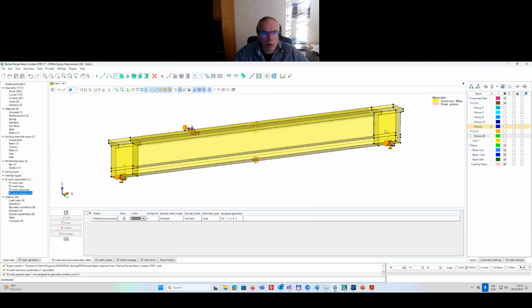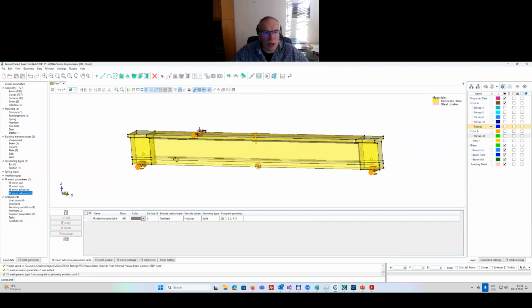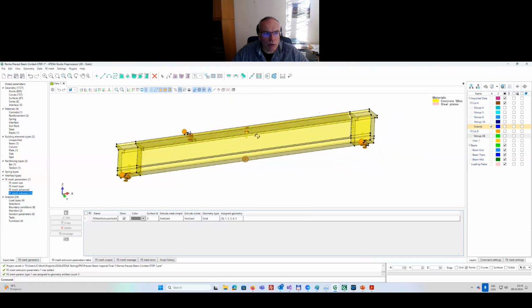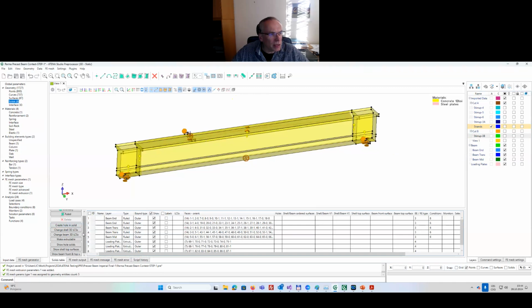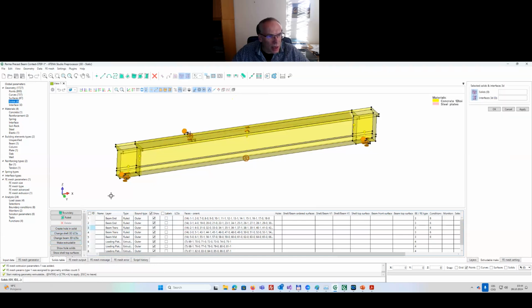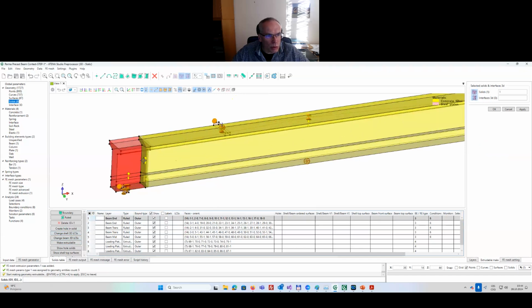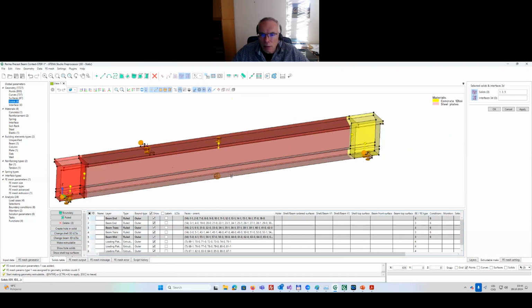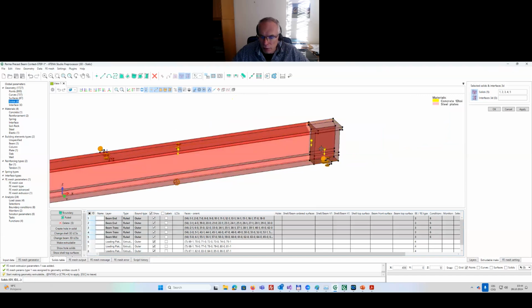We want them to be extrude, but to be able to use extrude, we need to make sure that all these regions are compatible so that the extrusion will be the same along the whole length of the beam. Therefore we need to go check and verify whether these volumes are compatible with each other. And this is done through this make extrudable command in the solids table. So I select this make extrudable. It asks me to select the volumes that I want to make extrudable, and I select again all of them.